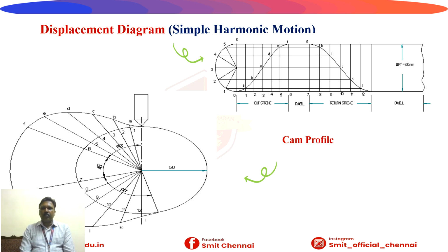We can divide into some more equal parts also, but for easy understanding, we can go with 6 equal parts. After dividing into 6 equal parts, the height of the diagram is 50, that is the lift of the stroke. It is given in the question. Now on the left hand side, to get the cam profile, we have to fix the angles first. What are the angles you have to fix?